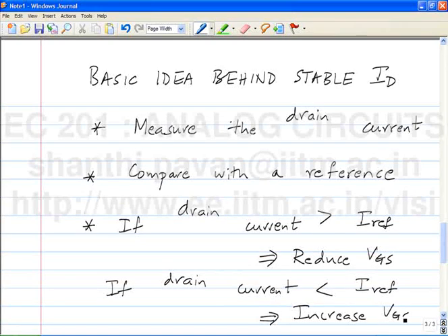Okay, how do we get a current source? For the time being, assume that it's a given. All right. It turns out that there are ways of generating current sources using transistors. Now that you already know how a transistor works, if I had a stable voltage source, I could apply it across the gate source of a transistor, and then the drain current will be a current source. That's a very cheap way of doing it, and it's a bad way because the current will keep varying when the threshold changes. But there are lots of ways in which you can get rid of all these things. But for the time being, assume that a current source is God given and exists just like a voltage source is God given. So everybody understands the basic idea, right?